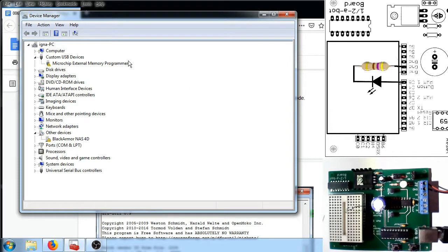The bootloader sometimes misidentifies itself to the computer. So what you need to do when this happens is you can either just hold in the button and press reset, and then it will a lot of times sort itself out like that. So if you get an error where there is no loader present, that is the fix. Right.